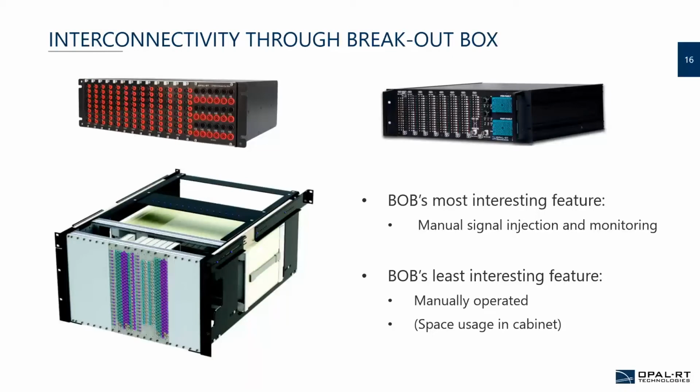That saved me a lot of trouble many times. Imagine a controller has many communication buses. For some reason, one of them gets damaged or doesn't work as you expected, and you want to test that. A breakout unit like that gives you an easy connection without opening the test bench to isolate the bus, and maybe just with wires swap two buses internally in the bench. That could be really useful.